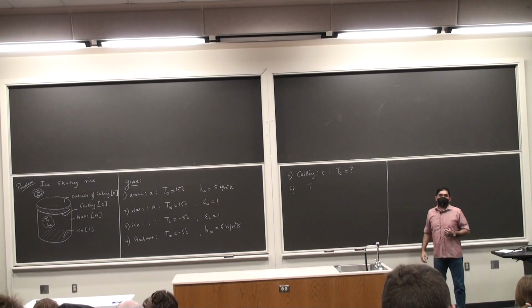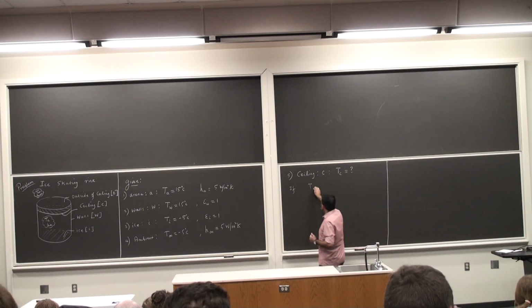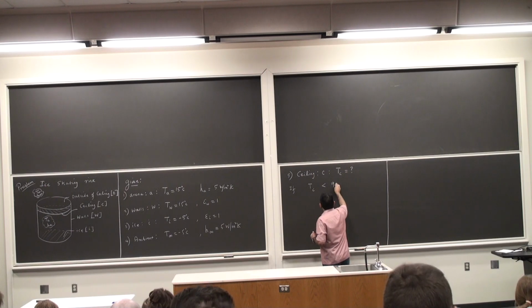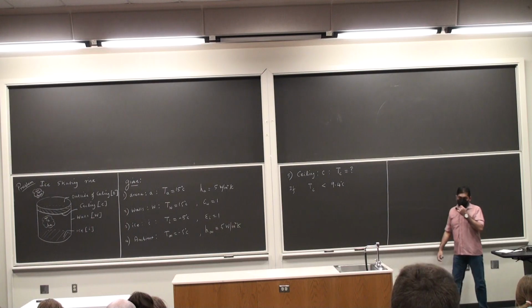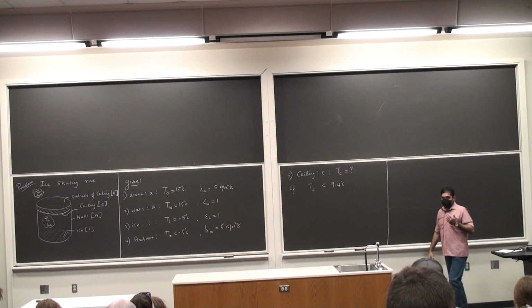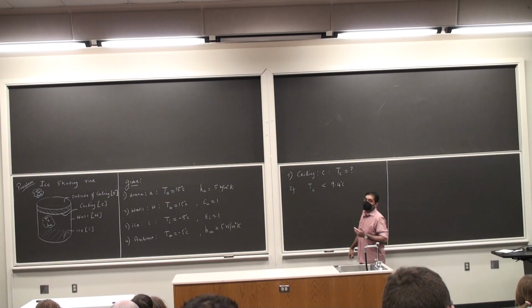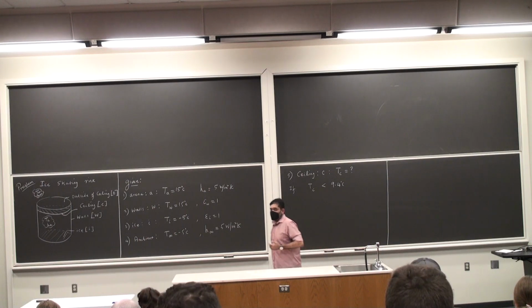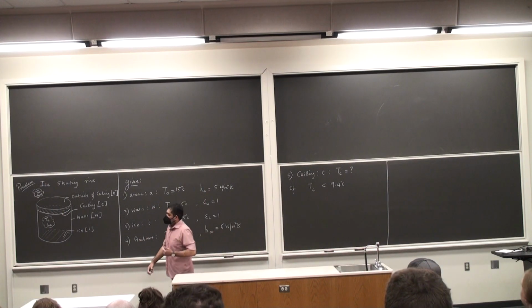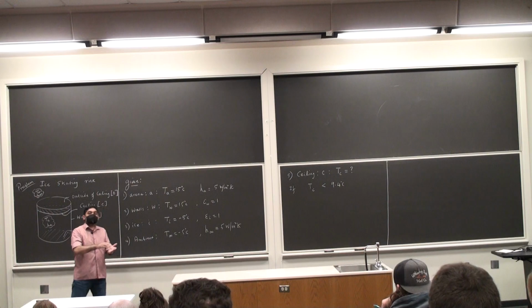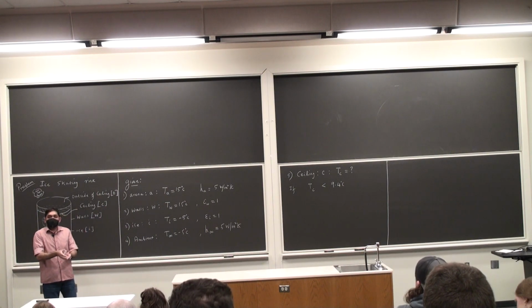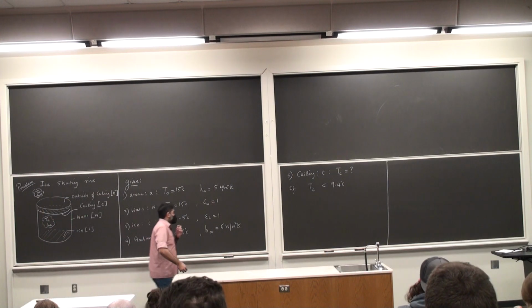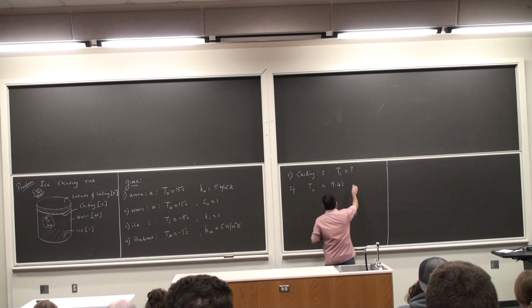But if the temperature of the ceiling falls below 9.4 degrees Celsius, then all of the water vapor will start condensing onto the ice floor. As water falls on the ice floor, it will start creating small bumps on the ice floor, and obviously this is not good for playing a game or for skating. So if T_c falls below 9.4 degrees Celsius,